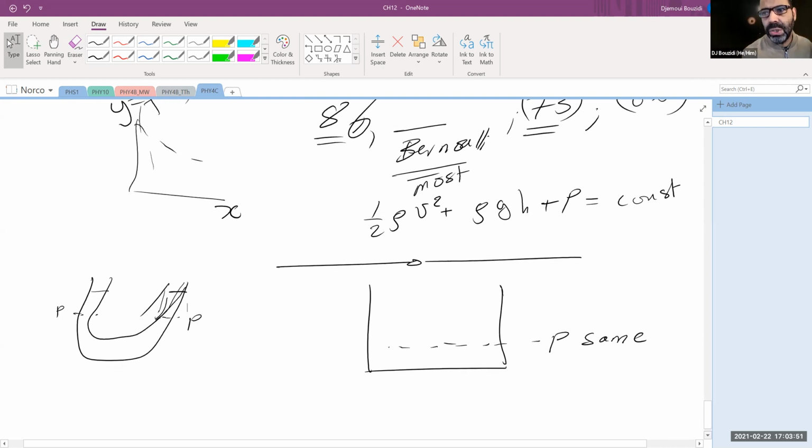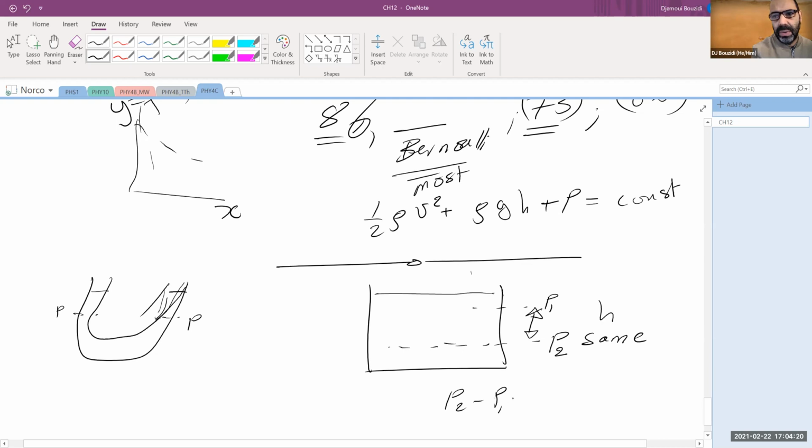So that's one thing. The other thing also is that the gauge pressure, it's very important to have an understanding that there is a difference between the gauge pressure and the absolute pressure. The gauge pressure is what is read at this point, okay? Versus a difference of some sort, okay? So for example, I have P1 in here, I have P2 in here. This difference in pressure is related to the height difference, okay? And basically we arrive at P2 minus P1 is equal to rho times g times the difference in depths, h2 minus h1, okay? So that is the value.